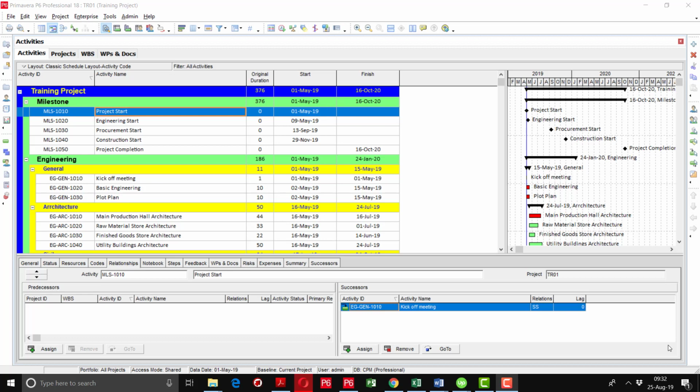you have a foundation that is going to be completed on 15th of April, but its equipment is coming on 25th of April, so you cannot install the equipment before 26th, regardless of whether the equipment foundation has been completed or not. For such activities which are not in our control, we have to apply constraints so that we can see the impact of those constraints as well.